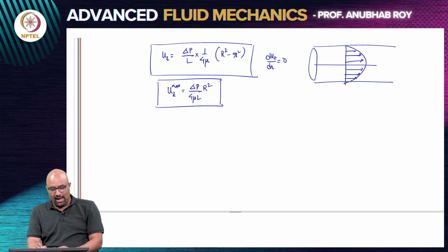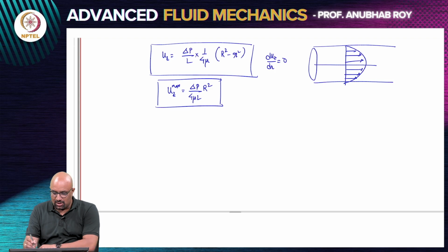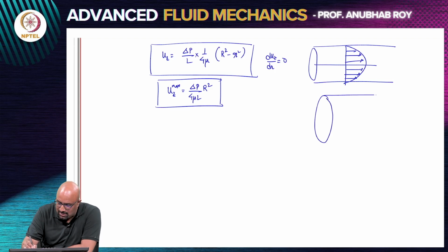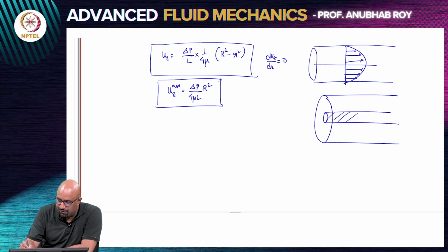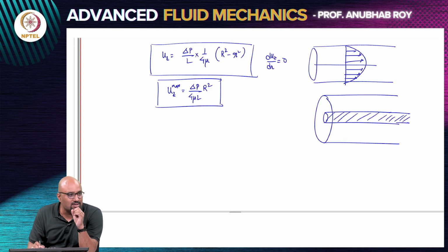Now, the argument for dropping the log, which was given by saying that the flow field should not become infinitely large in the domain, you can also arrive at it from a different way. This different way is a little bit more tedious from an algebra point of view, but will give you the same conclusion. If you repeat this problem, instead of flow through a circular pipe where the entire core has flow, you have flow through a circular pipe with an annulus in between.